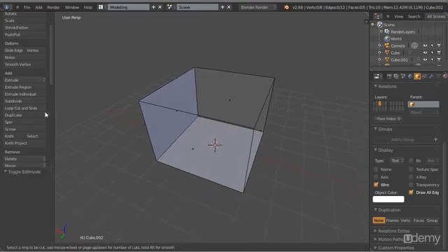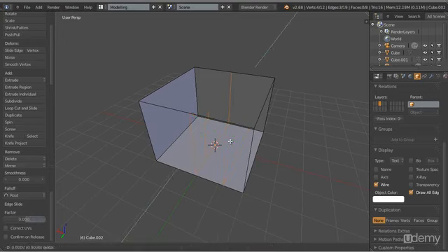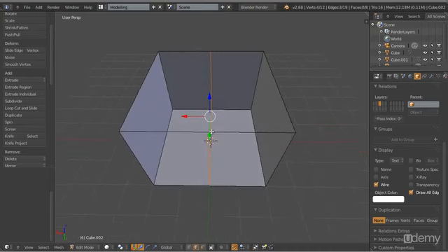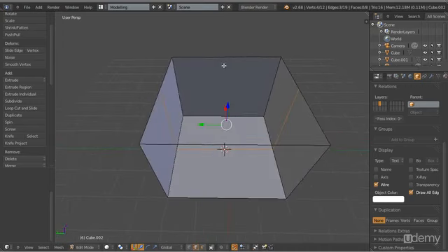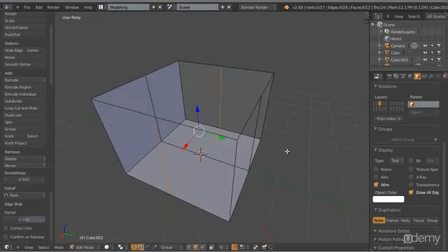So I'm going to choose Loop Cut and bring the edge loop here and click, and then press Enter on the keyboard. If I don't press Enter on the keyboard, I end up sliding the edge loop to all kinds of other places. If that happens, that's okay. You can just click to position the edge loop, and if you want to bring that back to the center, you can just move here where it says Factor, and I can just change that to 0 to reposition that back to the center of the cube. So we've inserted one edge loop here, and I want to insert another one across here. So I'm going to insert another edge loop here, press Enter on the keyboard to insert that there.